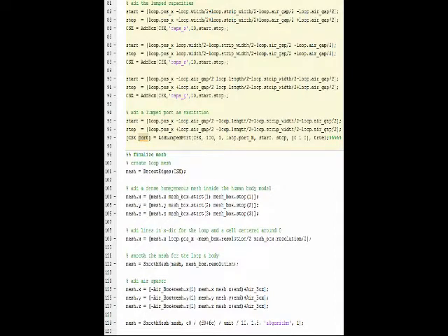Although the antenna structure has been finished, we still need to add some lumped capacitors and a lumped port as excitation points. We also repeat the same process. We have the starting point and stopping point, using the addBox function for creating the structure in the CSX parameter. Repeating this process, we finish this part.